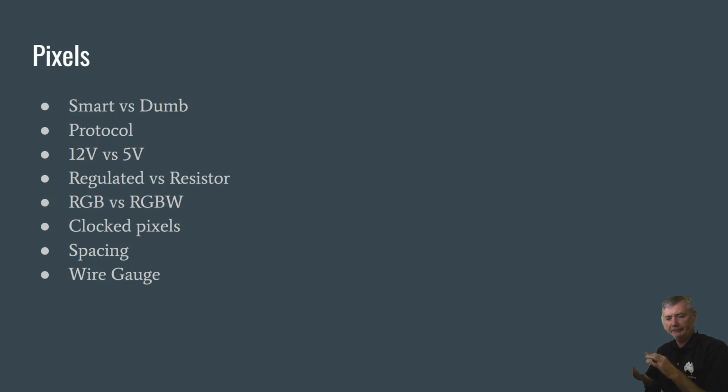You'll have to go with an Avatec or a Falcon, or I think the AlphaPixels also support clocked pixels. They're not as common, and to be honest, you don't really get the benefits that clocked pixels could offer, because the controllers don't generally support it. In theory you can run clocked pixels faster and get higher frame rates, but most of the controllers don't support them, other than maybe the Avitec, which do drive very high frame rates.